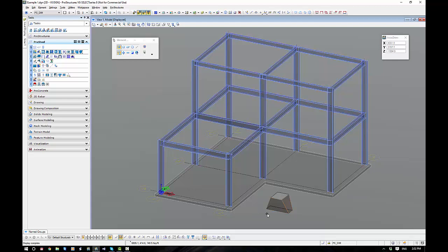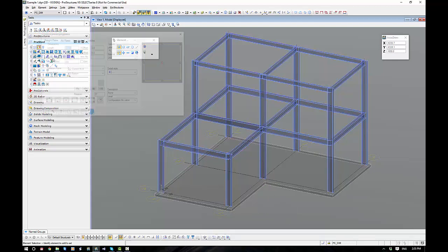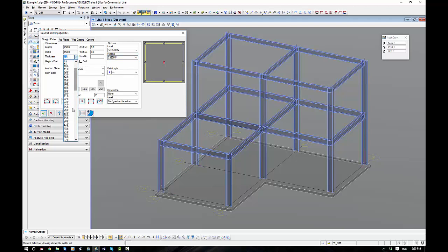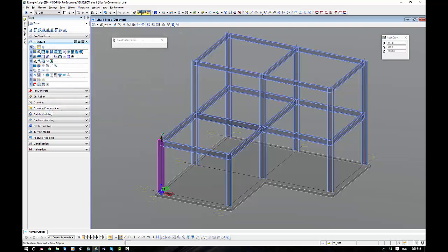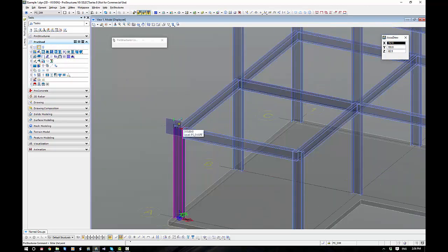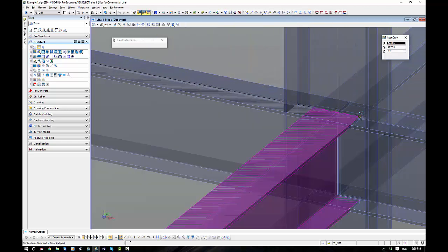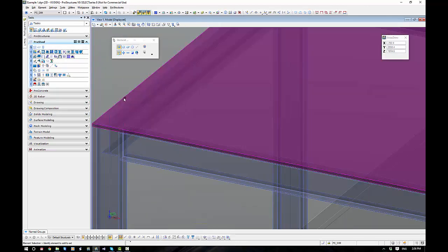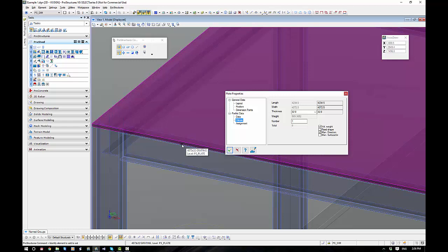Okay, so let's get rid of that hopper or the feed chute, and let's reset this time for grating. Okay, I'm going to show you how to do grating. Now we have a WebForge catalog in here. It has the specific gravity for each particular WebForge type so that the mass per square meter comes out correctly. So I want 32mm grating for C325MP. I'm going to pick it by corner. Remember, toggle the focal point by E. Okay, and it drops your panel in.